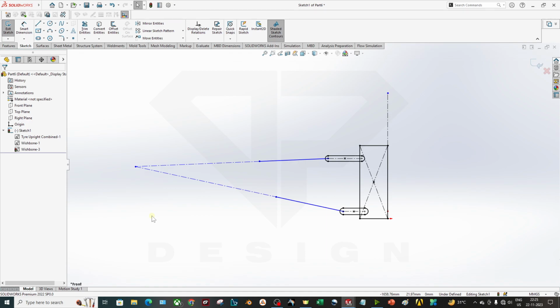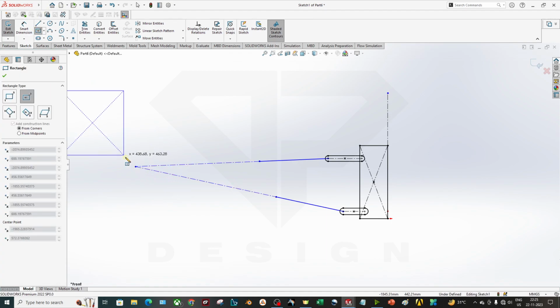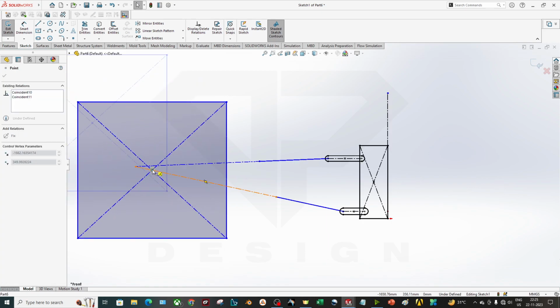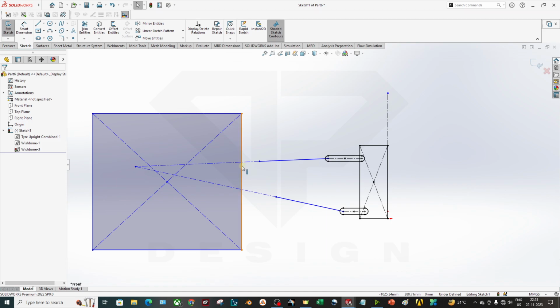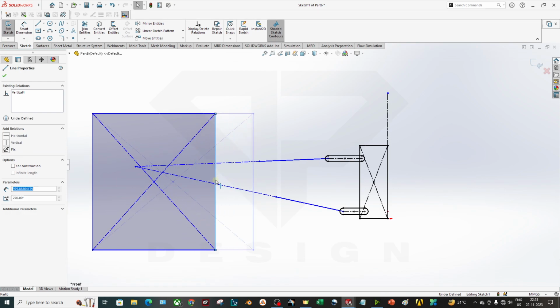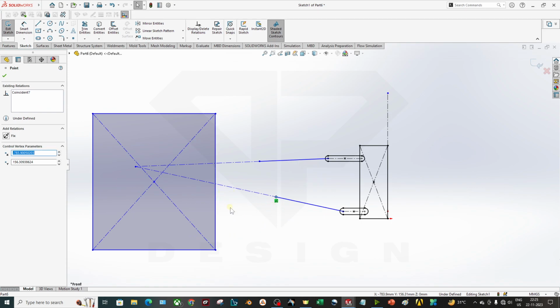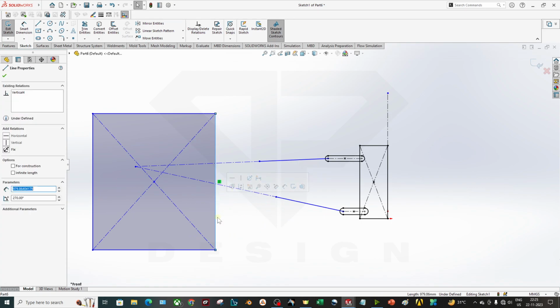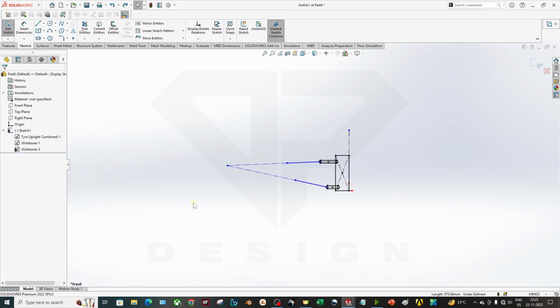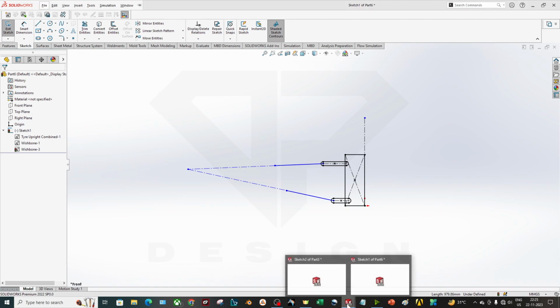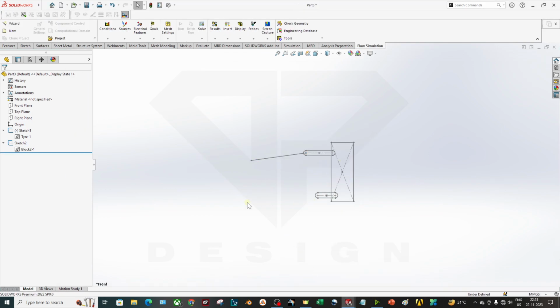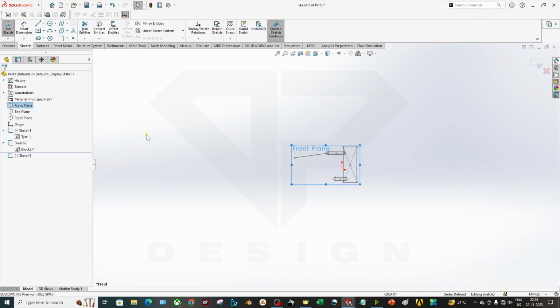Now coming back to our topic, you are going to build the whole geometry. So what you have to do is create a new body, like this is my car, right? And these are my wishbones. Now you have to create two mounting points where your suspension points will rest on the body. So this must be a block. You can create it in this panel also, but for better understanding, I will create it on this panel. So you will not have any confusion when making the body.